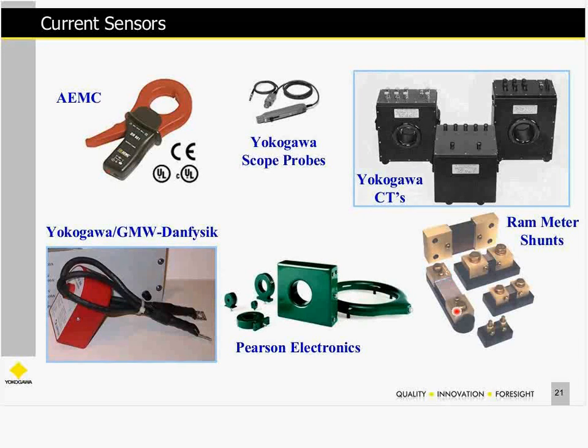They are for DC. Another popular current transformer is from Pearson Electronics. These are very high frequency coils, and if you're getting into real high frequency components and waveforms, used an awful lot in the lighting industries, electronic ballast, and things like that. So from Pearson Electronics. Then we also have another system, which is a precision measurement current transformer.